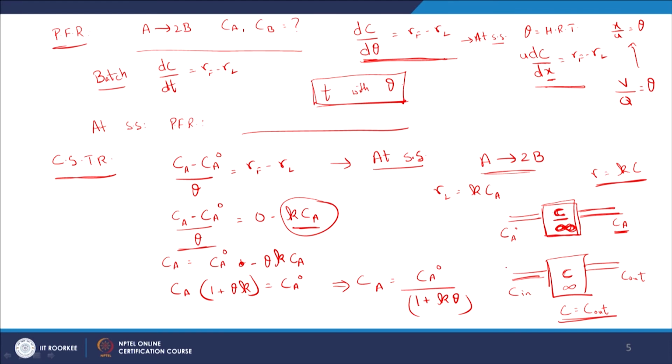Whatever is coming in is going to be instantaneously diluted, and then you will have the relevant equations, and then it's going to flow out, right. So obviously in a CSTR, the concentration inside the reactor and the concentration outside the reactor are the same. That is the reason why when we are writing the rate of loss of this compound, we could directly write that as the concentration of A that's leaving the system or even within the system, which is going to be the same, right. So that's the aspect here.